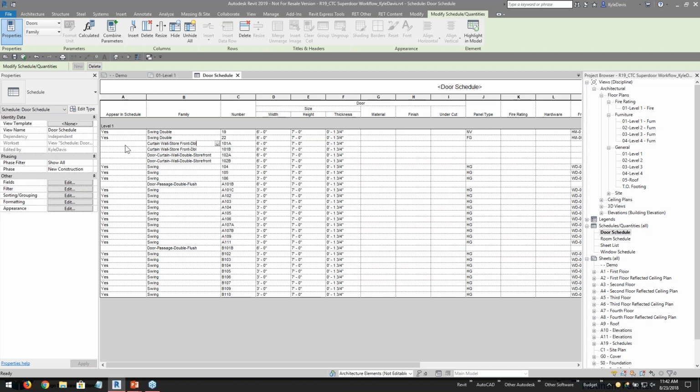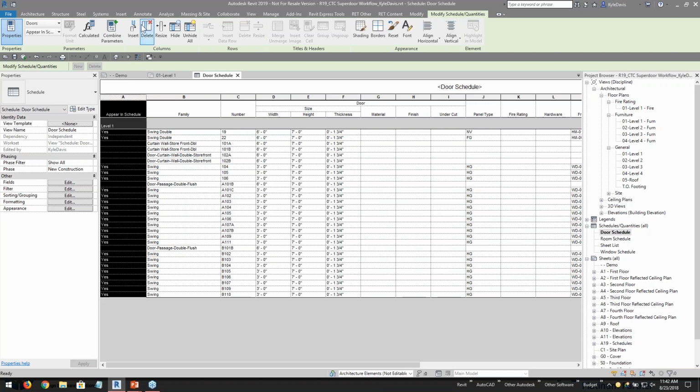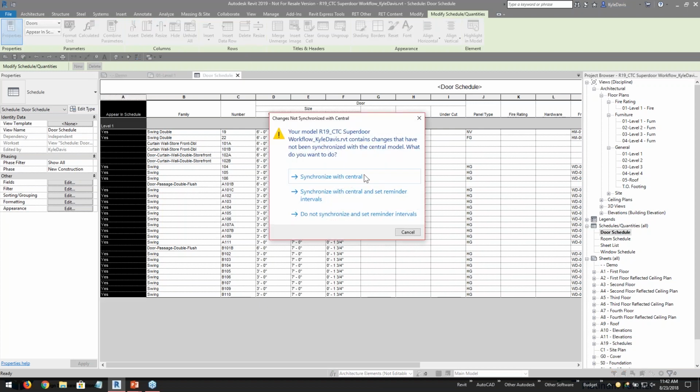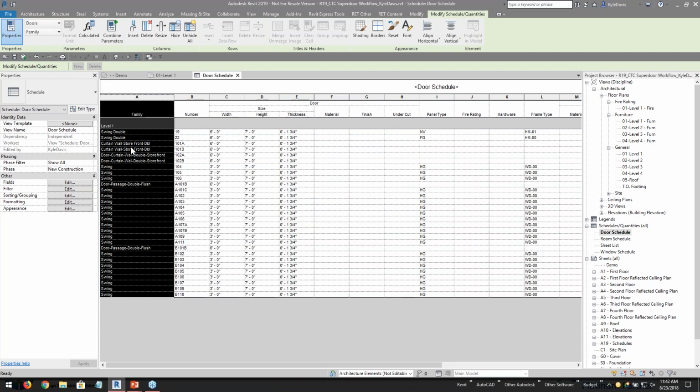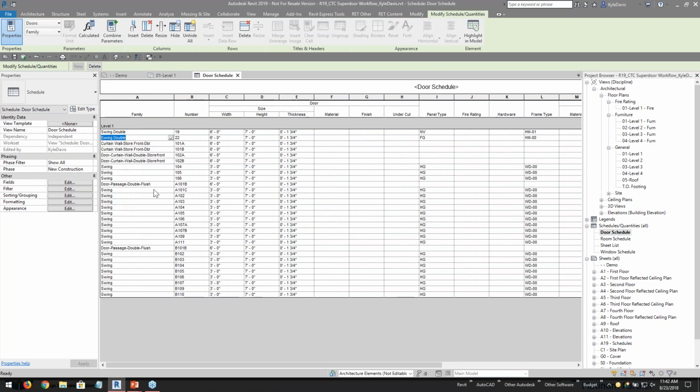We put a formula in there to lock them at no, and the main assembly is locked at yes. So here you can see these are all yeses, and the panels would have been no. Now again, I don't have to keep this one here. I can hide that column so that I don't see it, but it still filters my schedule.